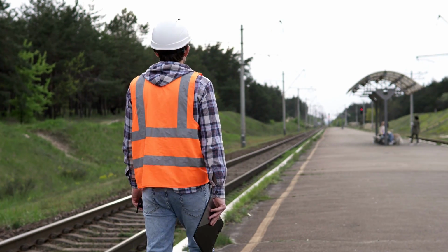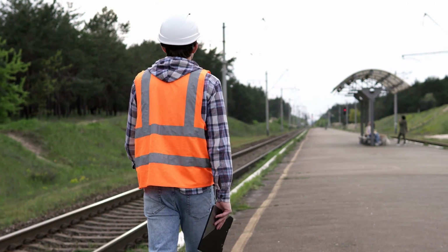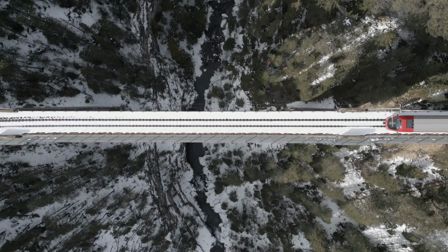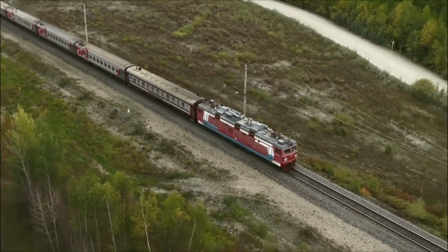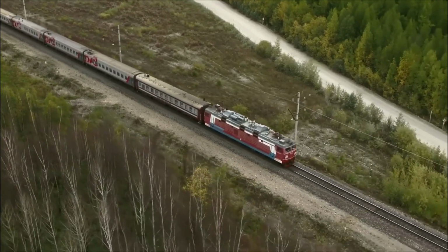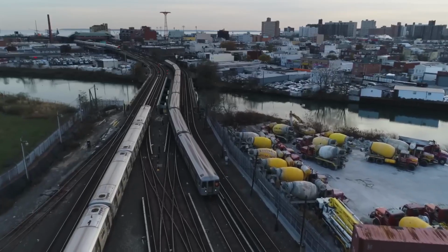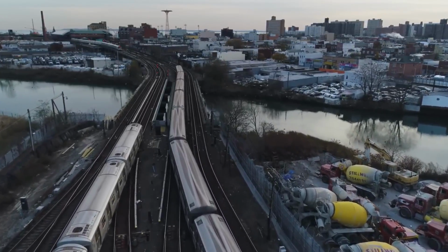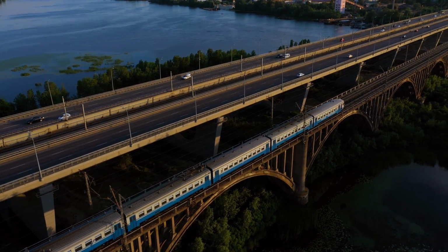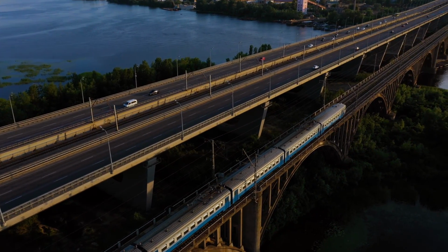You're walking the track, and the moment you step onto the bridge, you know the rules just changed. A geometry fault on plain line, you can tamp it, but on a bridge, it's just not that simple. The ballast might be shallow, that limits the tamping options. The sleepers can be tight to the structure, so slewing, again, not possible. And the track might be directly fixed to the bridge structure, so it's just not that easy.